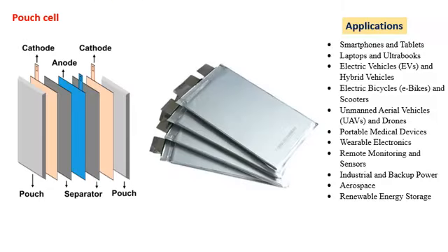Let's come to the other type of battery cell, that is the pouch cell. Have you seen the battery in your mobile? Yes, the mobile battery is a pouch cell. These different constructions are called form factors. If we talk about the construction, cathode, anode, and separator are common to all these cells. We have only three components: cathode, anode, and separator. And of course, casing. This is the pouch, which is made of polyethylene polymer. Actually, this is polymer coated aluminum foil.